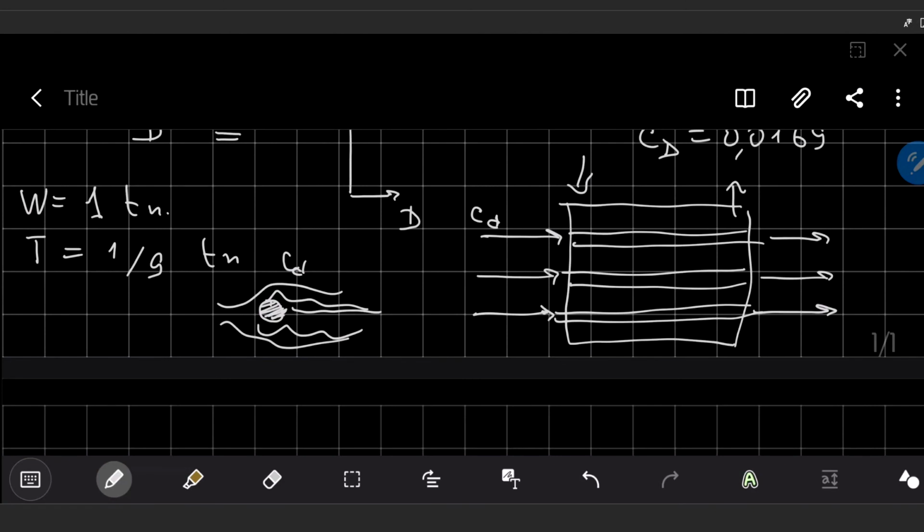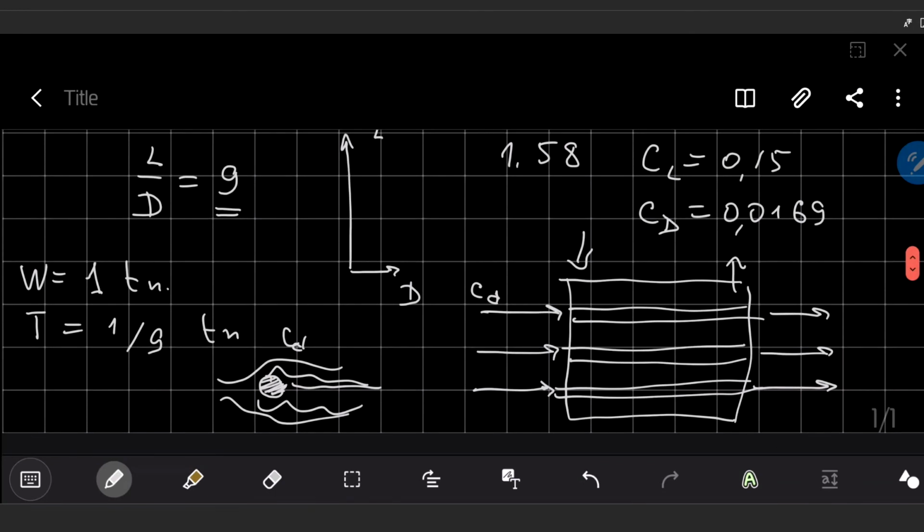Not big, very small drag, but from one device to another, you increase the drag coefficient. From one device installed to another, you have bigger and bigger drag coefficient. So this means the following: if you design a perfect airplane, you have some very nice drag coefficient, like shown here. If you install additional equipment, your drag coefficient will increase more and more and more, depending on how much you disturb the external flow.